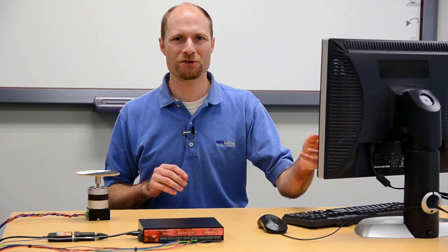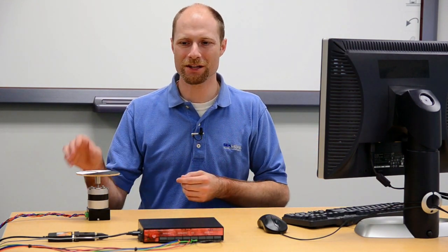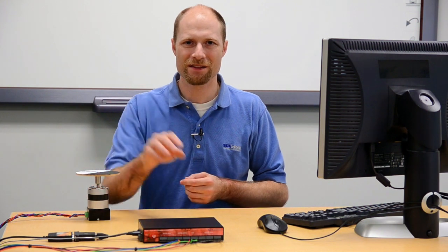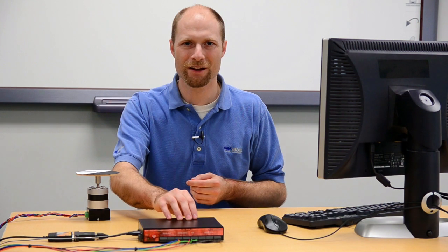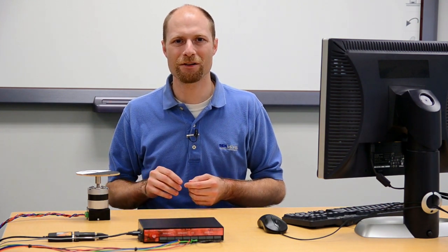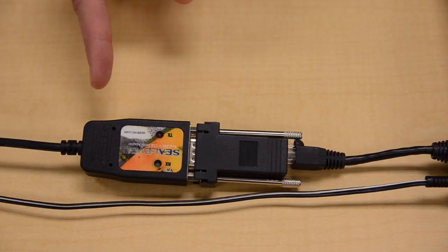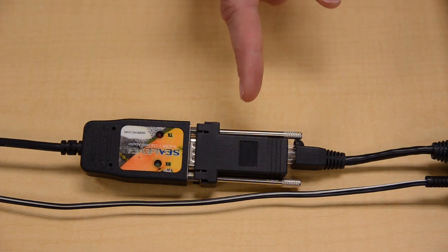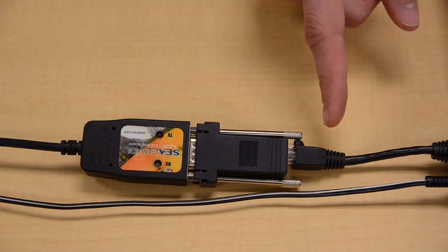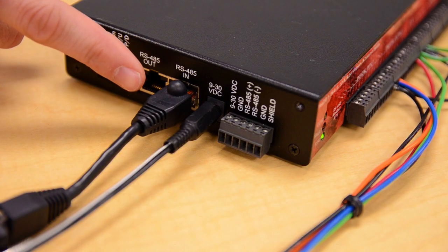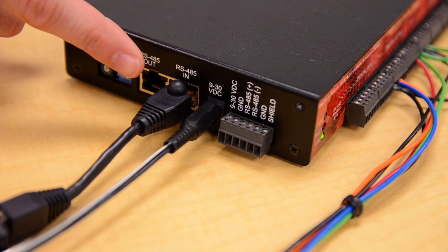Here I've put together a demo showing DAQfactory and our CIO 470M module controlling a motor. This CIO 470 module connects to the computer via RS-485 and uses the Modbus RTU protocol. I added a serial port to the host computer using a Sealevel 2107 USB to RS-485 converter. I used a DB9 to RJ45 modular adapter with an RS-485 interconnect cable and plugged the RJ45 cable into one of the RS-485 connectors on the 470 module.